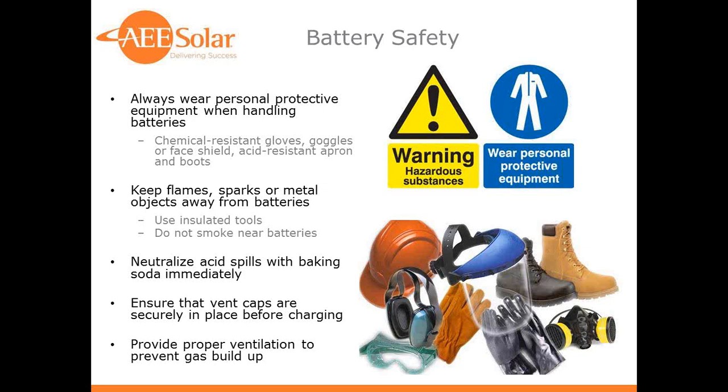Keep all sparks, flames, or metal objects away from batteries. It's a good idea to not wear any jewelry, especially hanging necklaces and other things, or rings on your fingers that are metallic. You don't want to do that because you're dealing with some live posts, and you can certainly hurt yourself by having metal contact live parts. So make sure you're not doing that.